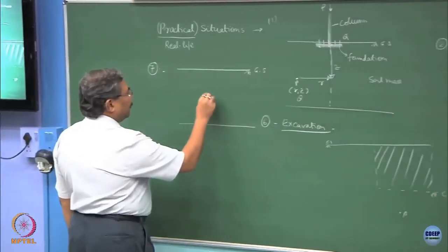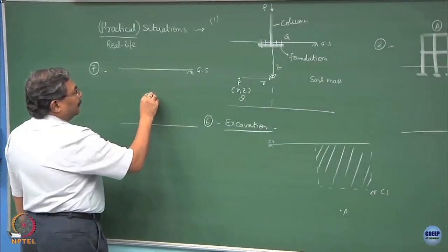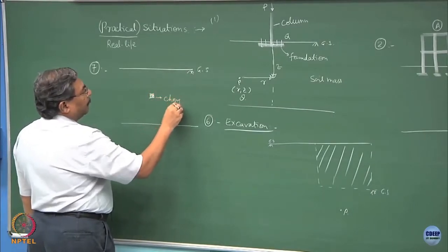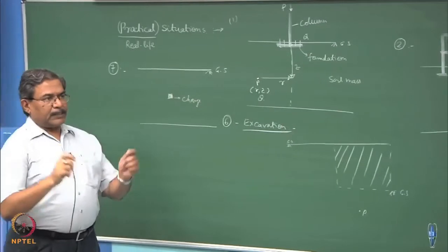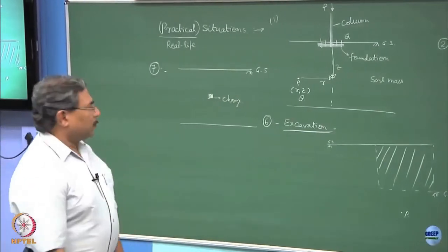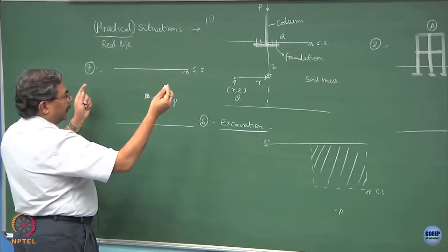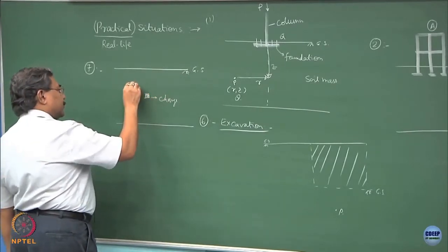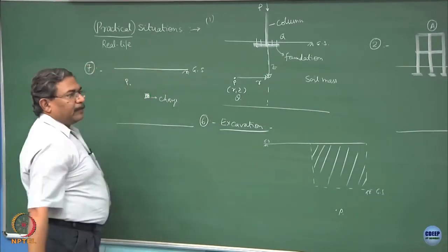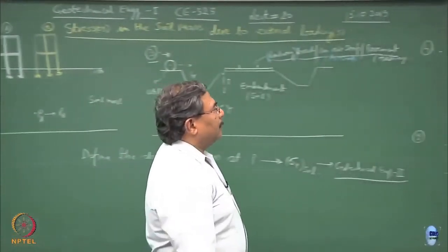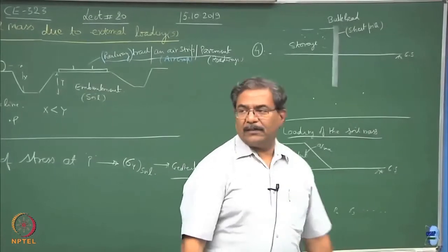So, what I will do is I will bury the charge over here and I can charge it. So, what is going to happen? This is going to create shear waves, compression waves, and because of this the state of stress is going to change at point P. So, these are very critical situations which you may come across, alright.